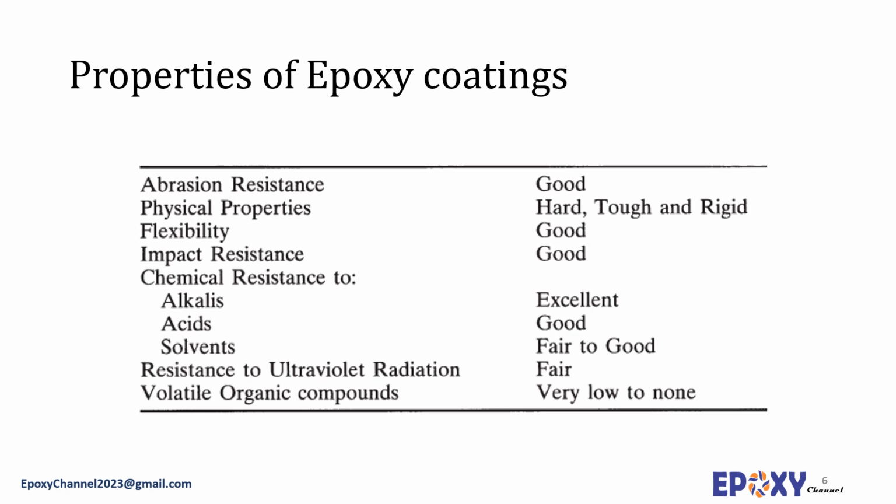Epoxies show unique properties which can be used in coating applications. There are no volatiles involved in these systems and they have good mechanical, chemical, and electrical properties, relatively low shrinkage during curing, excellent protective features, and perfectly tunable rheological properties. Moreover, the versatility of curative agents makes it possible to formulate epoxy coatings to be cured either at ambient temperatures or at elevated temperatures.